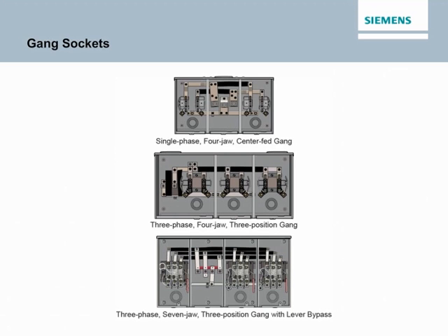Multi-position sockets, also called gang sockets, group multiple sockets in a pole section in the same enclosure. In general, gang sockets have the same features as single-position sockets. Available configurations include 2-position through 6-position gang sockets in a horizontal design and 2-position or 3-position gang sockets in a vertical design. A gang socket can come with no bypass, a horn bypass, or a lever bypass on each socket.